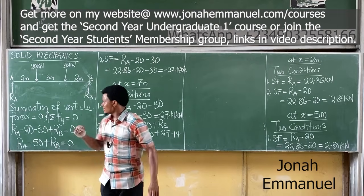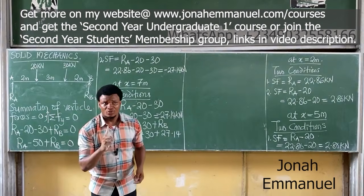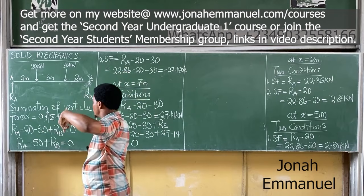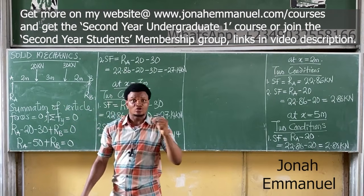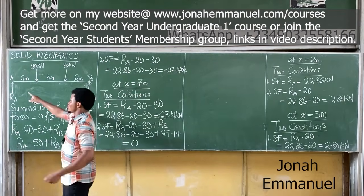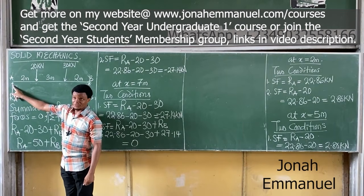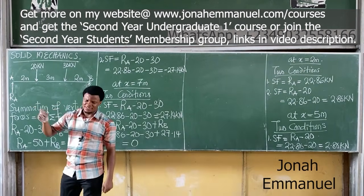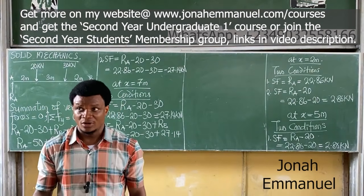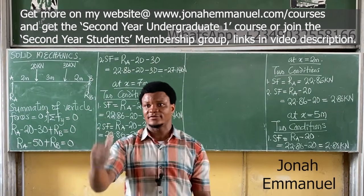Check our first example. Our first example did not end with zero, but check what the shear force at x equal to 0 was. What was the first value? It was RA, which was 22.86. So here's the thing: shear force does not have to start with 0. In some instances, it will start with 0. We'll look at it. But always note this: shear force may or may not start with 0, but it must end with 0. That's it.